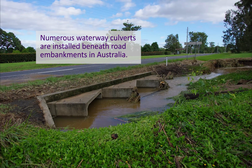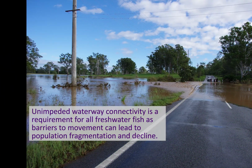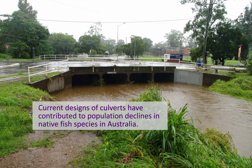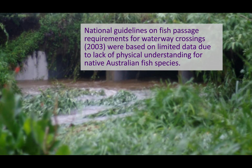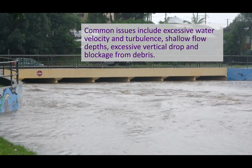Waterway culverts installed beneath road embankments are very common in Australia. All freshwater fish require unimpeded waterway connectivity, as barriers to movement can lead to population fragmentation and decline. Current designs of culverts have contributed to population declines in native fish species in Australia, as national guidelines on fish passage requirements for waterway crossings were based on mostly data from European fish species.